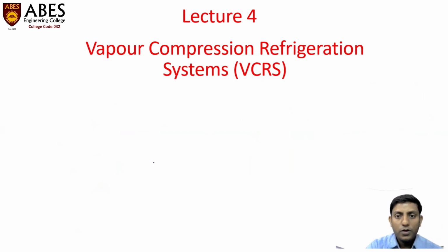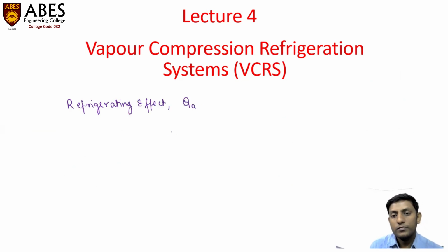From our understanding of thermodynamic cycles, the refrigerating effect, which is nothing but QA, involved in process 4 to 1, can be given by H1 minus H4.